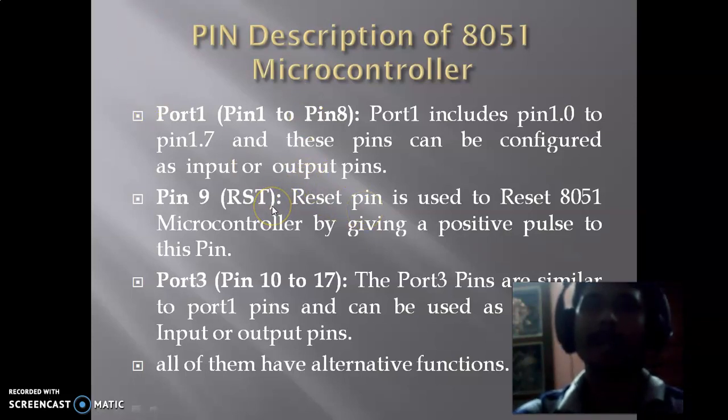And pin number 9 is RST, meaning the reset pin, and the reset pin is used to reset the 8051 microcontroller, and it is an active high signal we have to provide to reset the 8051 microcontroller.